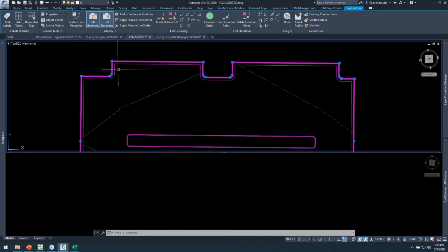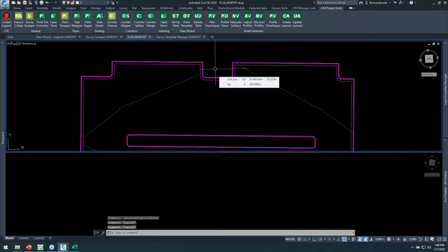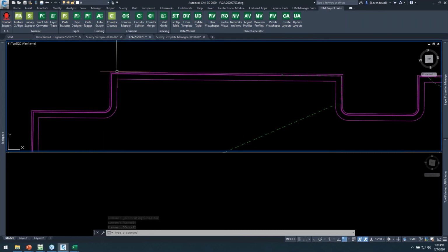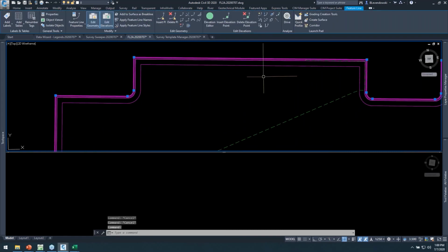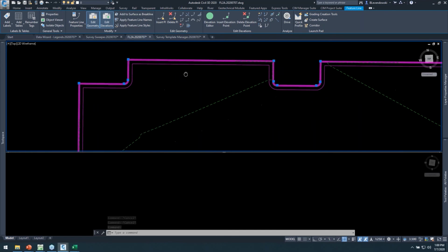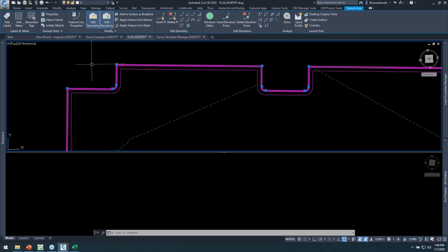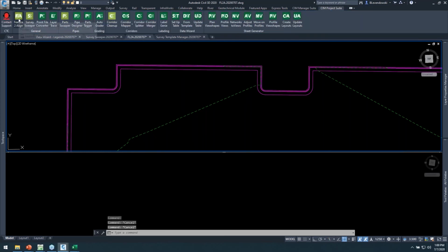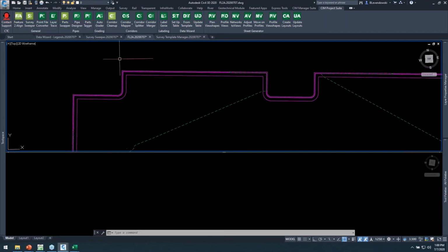Some of you might be used to generating a bunch of COGO points, something like that. Well, if you're able to stake a 3D line, it's much more flexible in your data collector. The only problem with this is feature lines won't load into your Trimble and your Topcon and your Leica data collectors. They need to be in the format of an alignment and profile. And in Civil 3D, there's no way to do that, which is the point of this tool. So it was this brick wall we had found in the whole process where we've got all these feature lines, the data is there, I just need to put those in my data collector, but we need those in alignments and profiles.